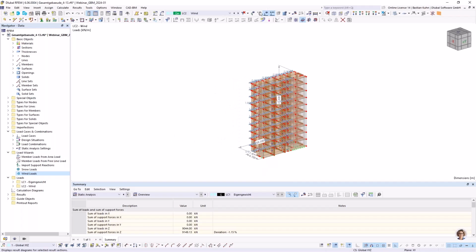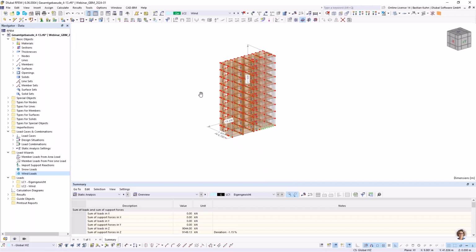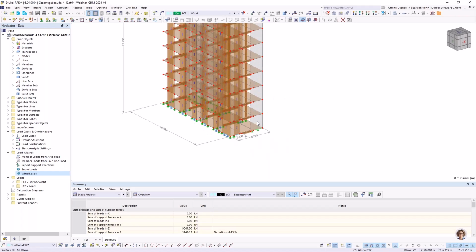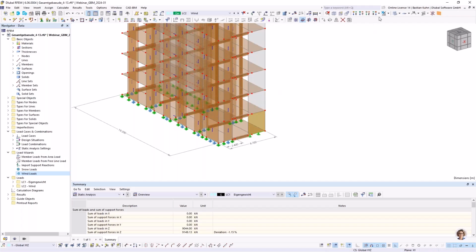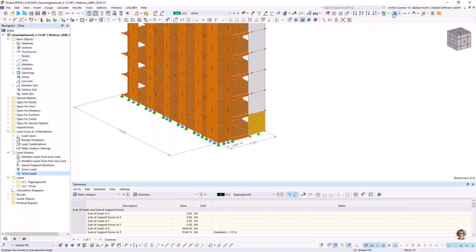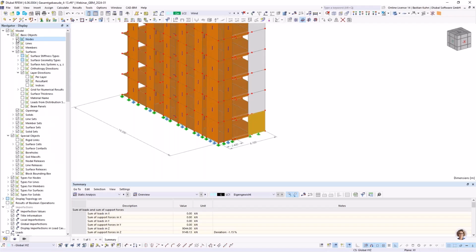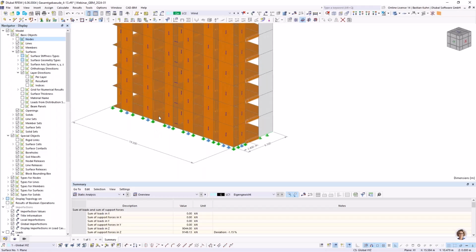Okay, I can switch off the load now in here. I mentioned it, take a look at the slab or at the walls. Slabs we did. Maybe if I put this on and we can get rid of the node, it's looking a little bit better. The stiffness direction, I don't know if you saw that when I mentioned it on the ground: I have an option for the CLT plates to show the resulting stiffness, and usually in walls in CLT plates, you always put the stiffness direction vertical, and on slabs, you put it horizontal. That's what this blue check should tell you.